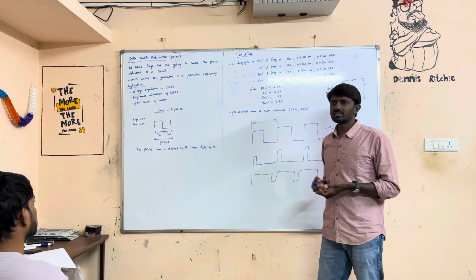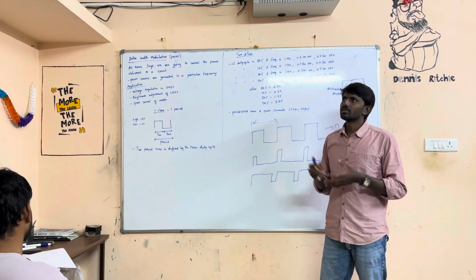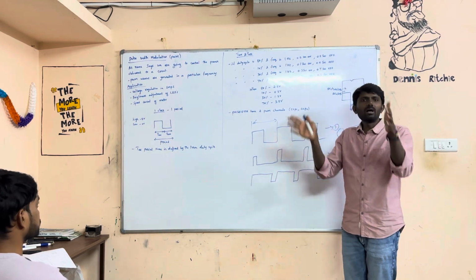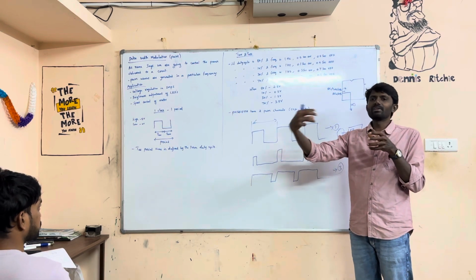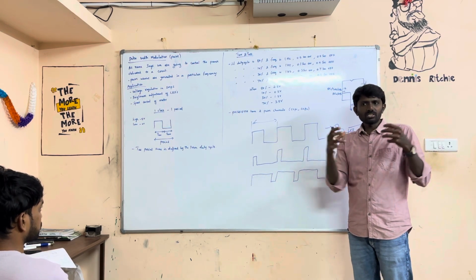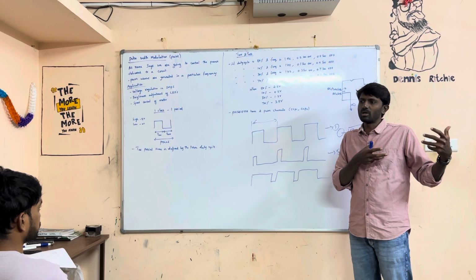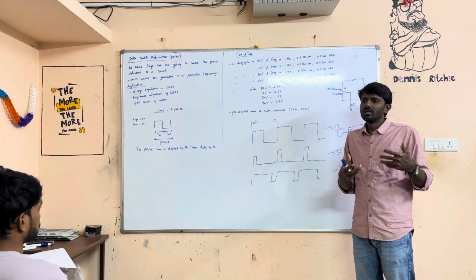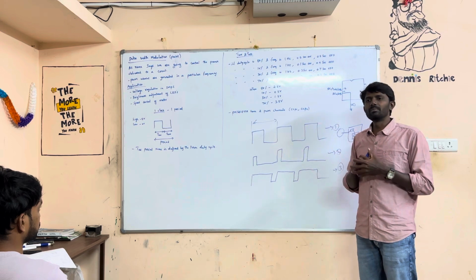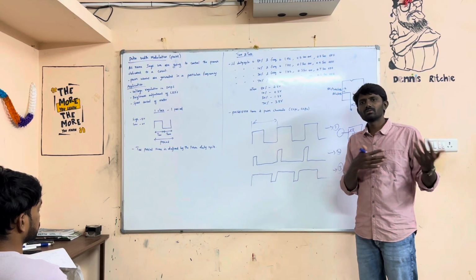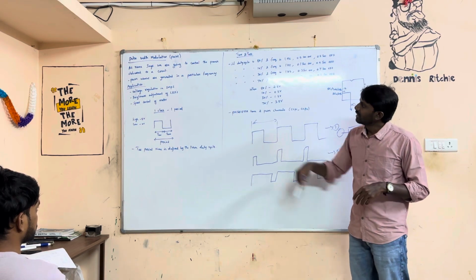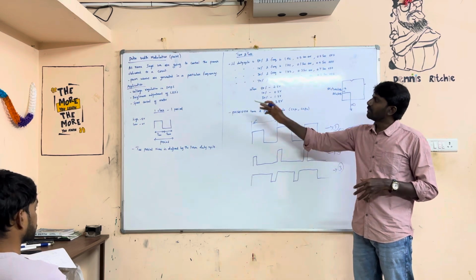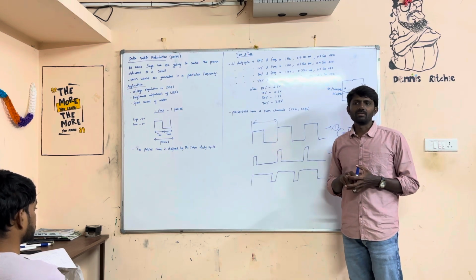SMPS we already discussed in our class itself. In the CPU box we are giving 230 volt. The 230 volt finally comes out as multiple small voltages, like 3 volt, 3.3 volt, 5 volt. There also PWM is used to convert it to different voltages. And the speed control of motor, brightness adjustment of the LED.